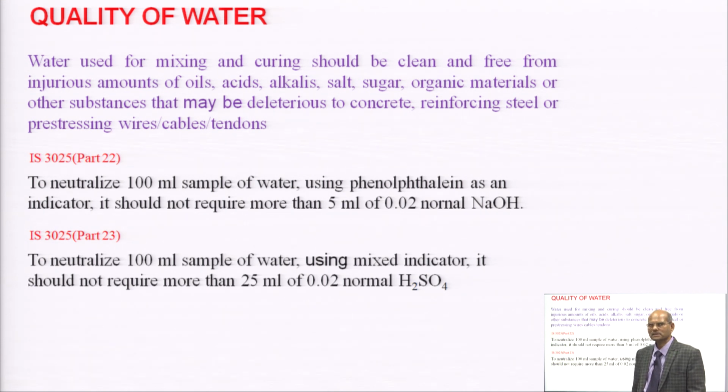So, the building was constructed around 25 years back, and most of the building is showing signs of cracks, because most of the builders constructed houses there using groundwater, and that groundwater contains a higher percentage of chlorides and sulphates than the permissible limits. So, that is a cause of creating cracks in the building.